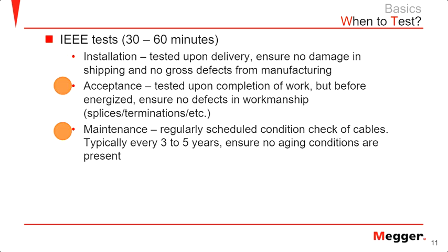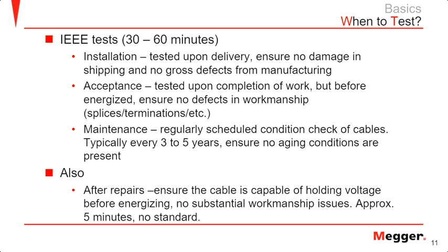And also, if you performed any repairs on the cable, you want to make sure that it is holding the voltage and there are no workmanship issues. So there is no specific standard around that, but typically people tend to say, hey, I'll just do a 5-minute quick VLF or 10-minute quick VLF just to say that, okay, everything works as it's supposed to, and now I can put it back into service.